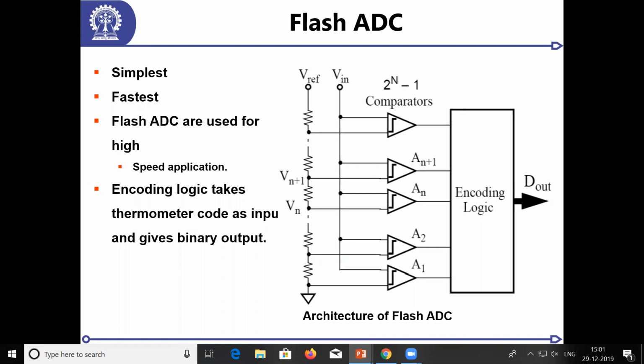Now, let me give you a simple example. Suppose I give you a black box and I tell you that the black box has a resistor and a capacitor. I don't tell you what the values are. I don't tell you what R and C are, and I ask, can you find out R and C? What will you do? I give you an oscilloscope, one capacitor and one resistor, and I tell you the values of those because I'm giving them to you. What is inside the box, you don't know.